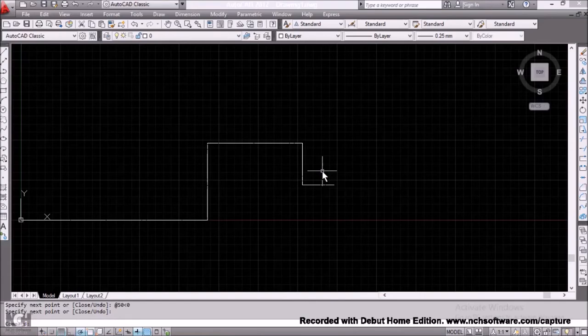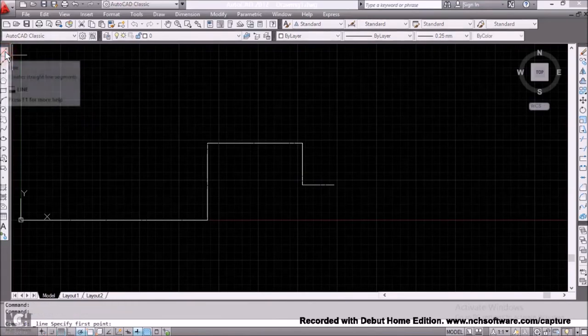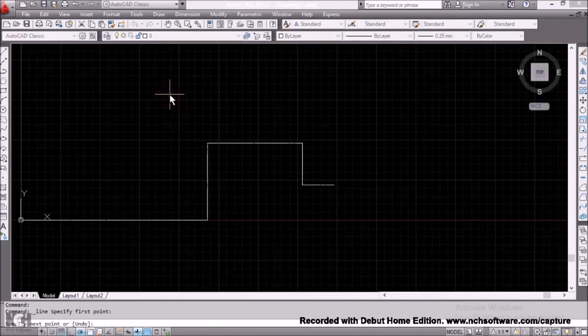It is very simple. Assuming I want to assign positions using the line tool, all I have to do is click the line command, and assuming I want here to be my starting point, I left click. If you want the line to be constrained to just 2 directions, you can click on the auto mode to make it straight. If I'm going along this direction, up to a distance of 300 millimeters, I just type 300 and I press enter on my keyboard.